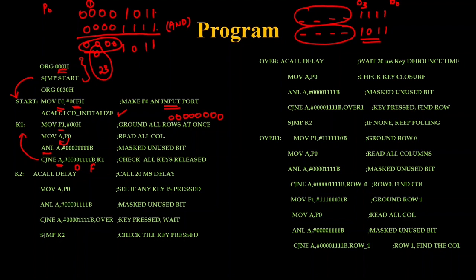Since it takes a very small number of cycles, we don't know whether it is happening or not. That much faster your processor computes, so it checks at the previous instant itself whether some key is being pressed or not. Wait till it becomes F, right? If it becomes F, come to the next line. So I am having a delay here. Why am I having a delay? Because every instant of time I have to make sure that I have a 20 millisecond delay.